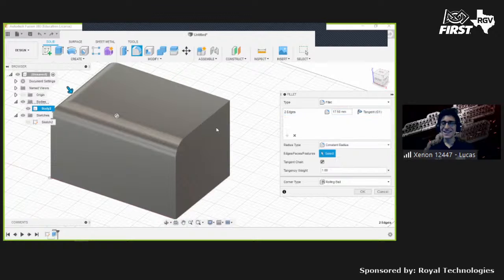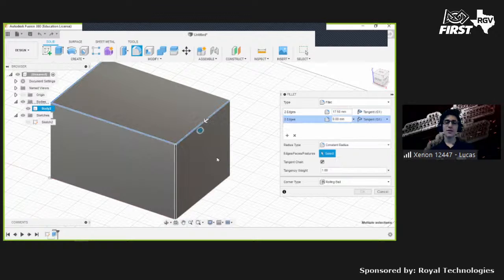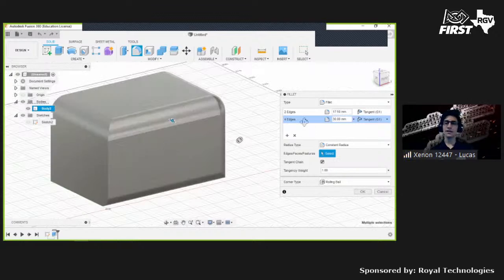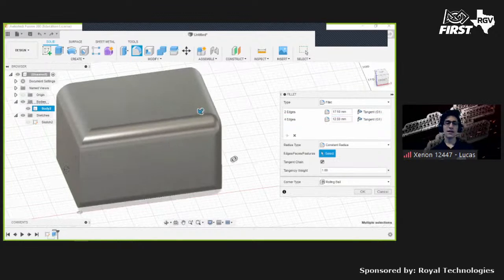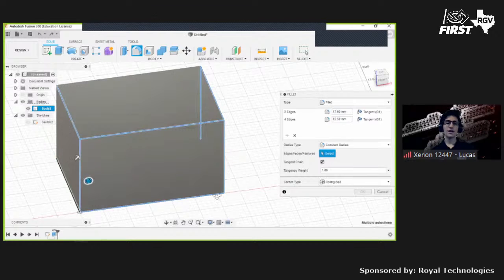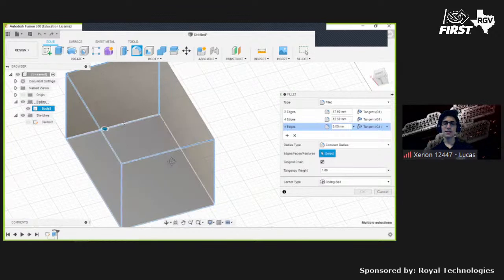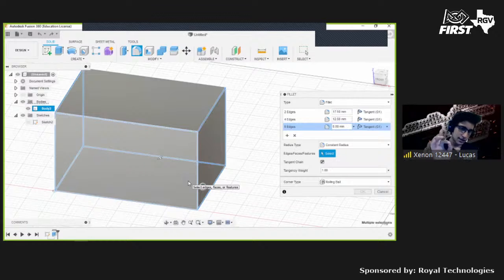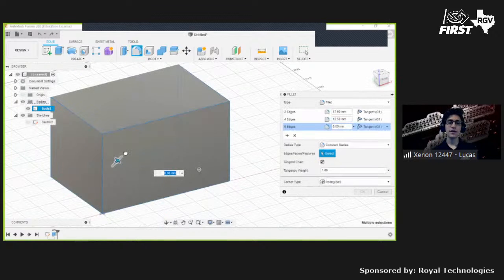All right. Let's go ahead and maybe add some more selections. And notice what's happening. If I click another line here, if I click all the lines of the part, maybe that side and that side. So if I click all the edges, now notice edges, not any part, but just edges. It rounds out edges. And you can use this bar to control exactly how far you want the edges to go in. And pull it in.